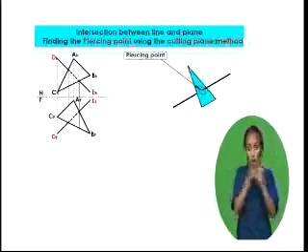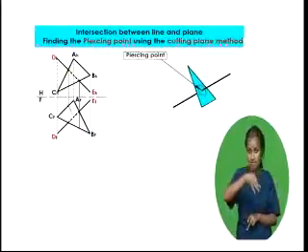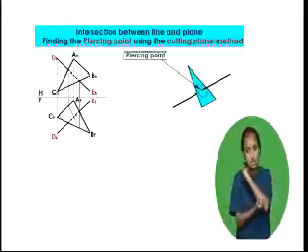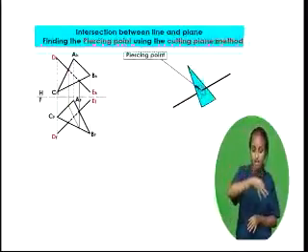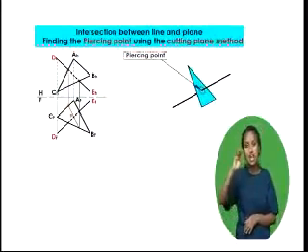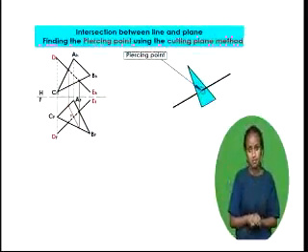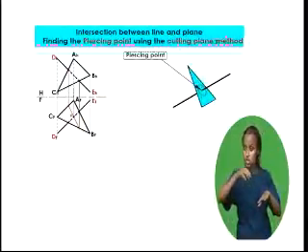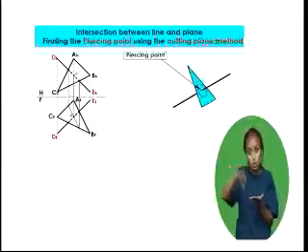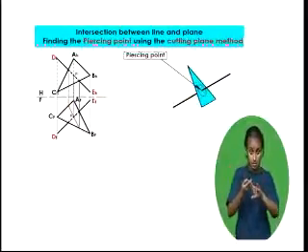Complete the line view RF, SF to establish P1F at the point of intersection of RF, SF and DF, EF. Locate P1H on RH, SH by projecting upward from P1F as shown in D.